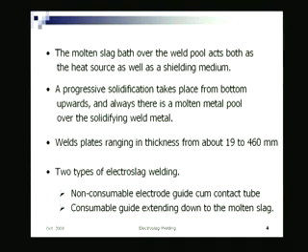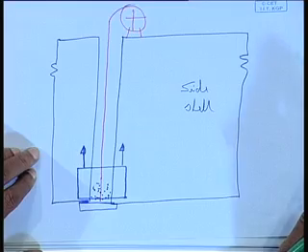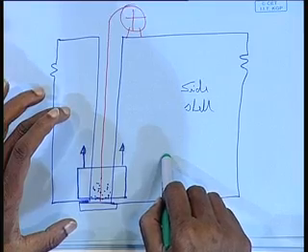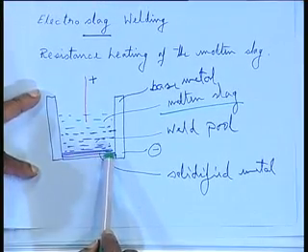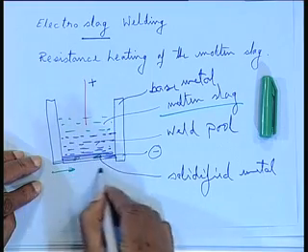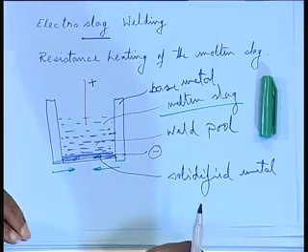No, that is a different issue. Here that does not happen, right. Because the thing is, firstly these types of welding are generally used in thicker sections, and whether it will close up or open out depends on the speed of the welding, how fast the contractional forces are working. As it is progressing up, your metal is getting solidified below. As the metal solidifies, the contractional forces will start working. So, they can give rise to a case of opening up, what you are mentioning, right.